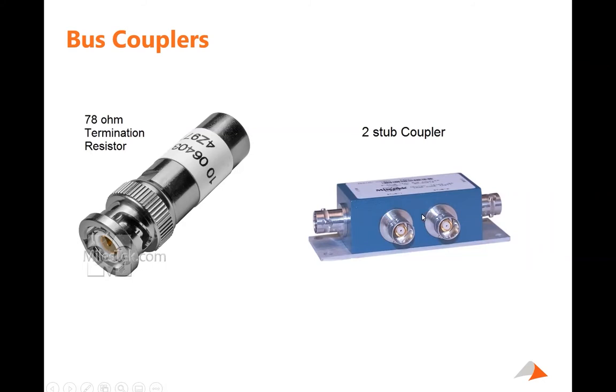What a lot of people will do in the lab is buy the size coupler. Maybe it's a 2-stub, maybe it's a 4-stub. I've seen people buy 12 or 16 stubs, just crazy stuff. And you can actually make that your data bus. You can take this terminator here and put one right there, and then take another one and put it right over here on the right side.